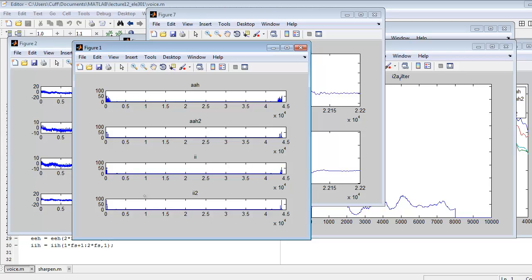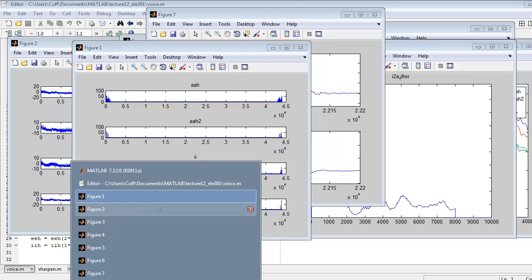Just to see what is the difference between sounds that are the same pitch. For example, this E sound and that ah sound are both set at the same pitch, but yet you can hear the difference. So let's look at what the difference is. Some of you who've played around with this looked at recordings of sound of different vowels, for example. Has anyone done that? A little bit here. It's a fun thing to do, and you say, how can I tell the difference here? And a lot of it has to do with the magnitude of the frequency response.